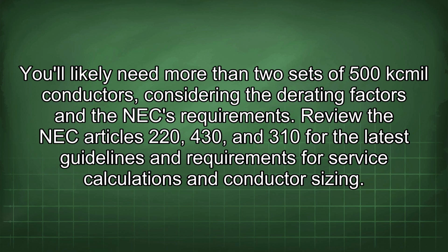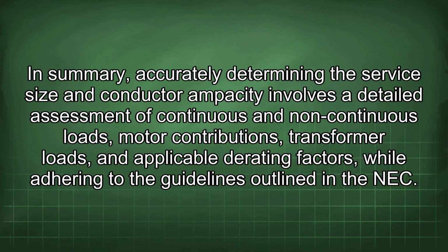Review the NEC articles 220, 430, and 310 for the latest guidelines and requirements for service calculations and conductor sizing. In summary, accurately determining the service size and conductor ampacity involves a detailed assessment of continuous and non-continuous loads, motor contributions, transformer loads, and applicable derating factors while adhering to the guidelines outlined in the NEC.